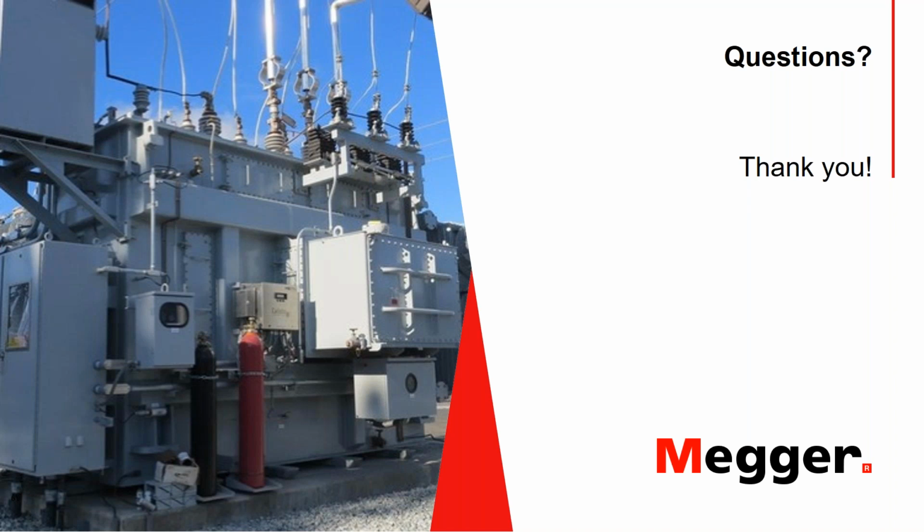Thank you, Dinesh. Additionally, while I have you, the next question will be for you. From experience, resistance measurements from tap 1 to 33 and 33 to 1 on OLTC give a slightly different result. Do you have any experience with this?